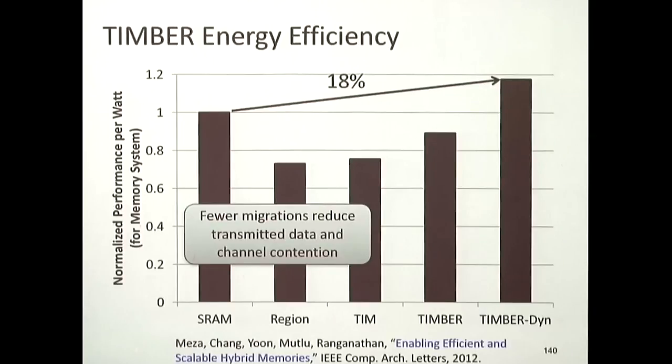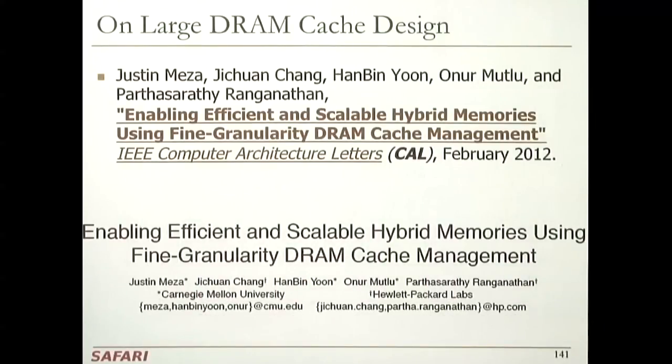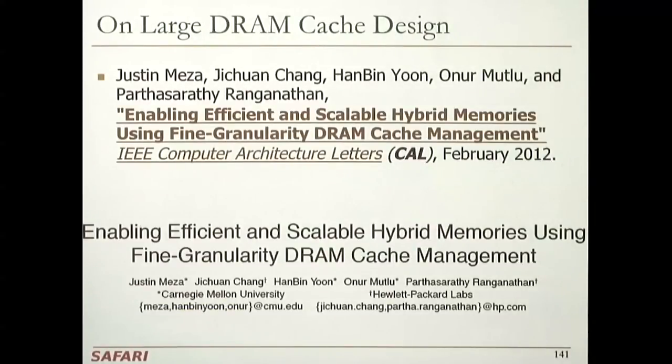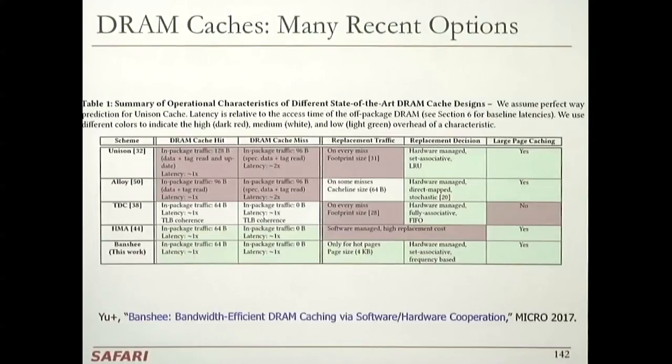And actually, the energy efficiency is better if you design a system like this, because the large SRAM tag store is very energy inefficient also. OK. Any questions? There's a huge design space, as you can see, right? I don't expect you to know all of the ideas. Just get the high-level ideas, basically. Caching the tags, for example, is a solution for not accessing DRAM twice.